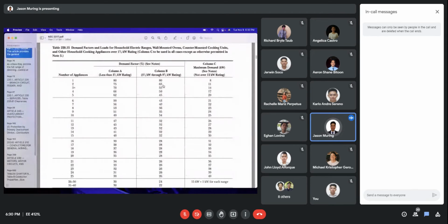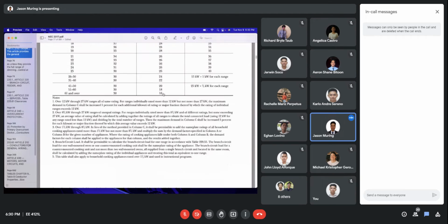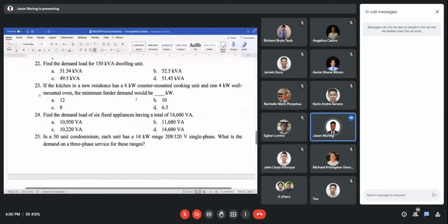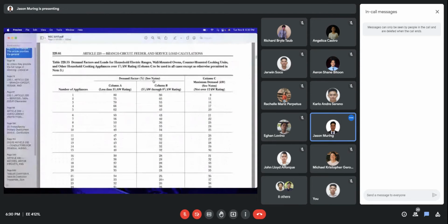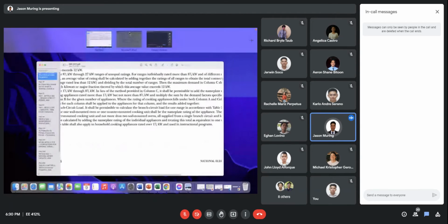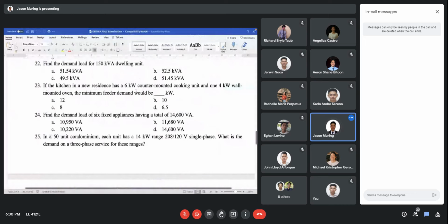6 and 4. So therefore, it now exceeds this column B because we have 6 kilowatt and 4 kilowatt. Again, since they are located in the same room, as given in the problem, not just the kitchen, and we supply the same feeder for these two loads, we can consider that they are connected into a single branch circuit.